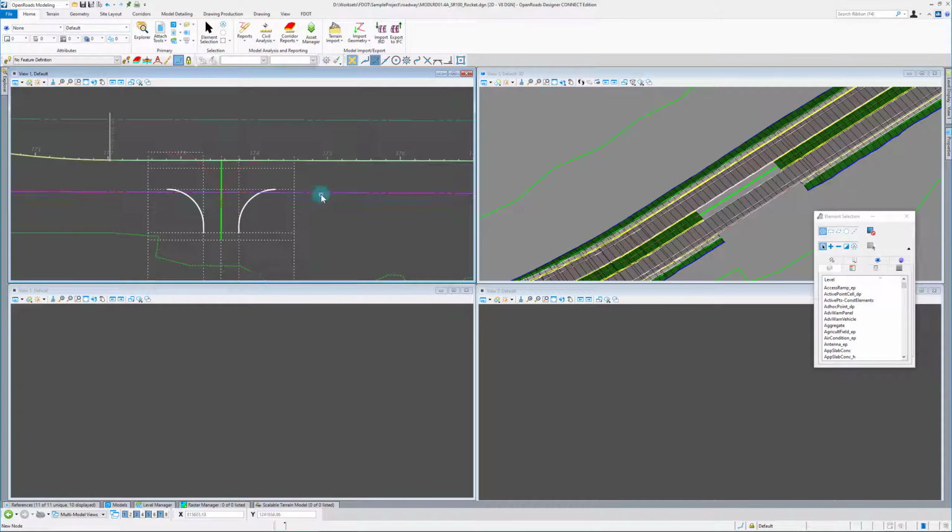If you remember from our last video, we set up our side street design here to just include the 2D portion of the design. So we set up the curb returns and the control radii so that we could clip our median out and clip our right end condition out at the appropriate locations. So what we're going to do now is start detail modeling this side street.